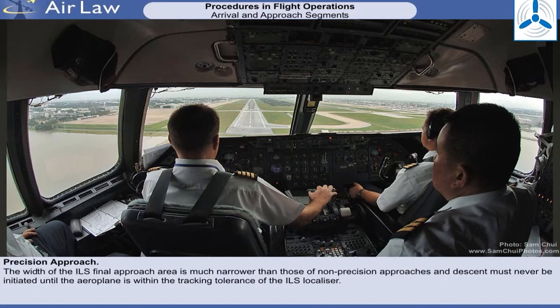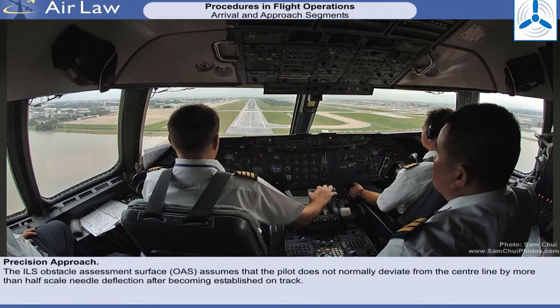The width of the ILS final approach area is much narrower than those of non-precision approaches, and descent must never be initiated until the aeroplane is within the tracking tolerance of the ILS localizer. The ILS Obstacle Assessment Surface, OAS, assumes that the pilot does not normally deviate from the center line by more than half-scale needle deflection after becoming established on track.